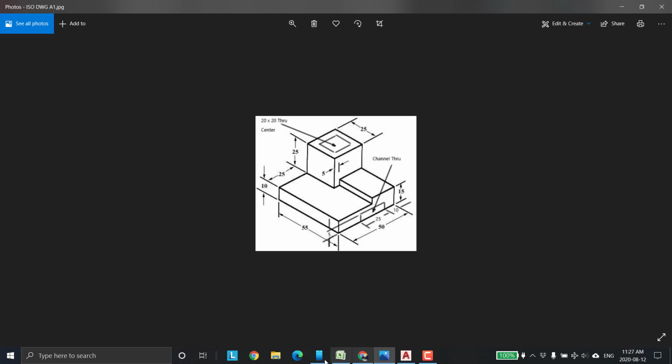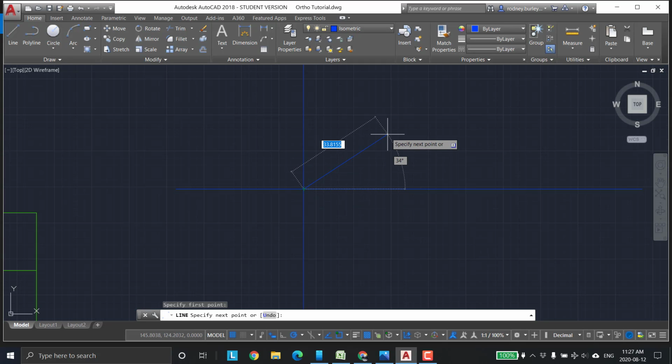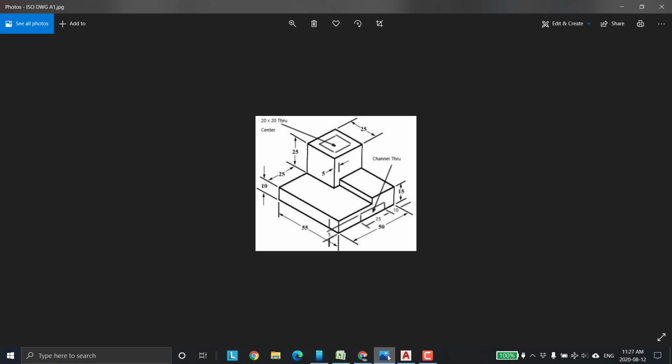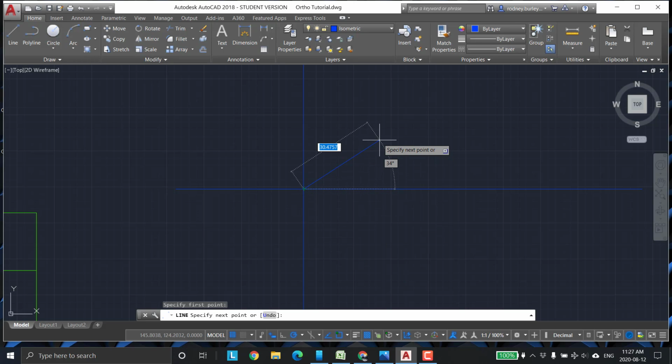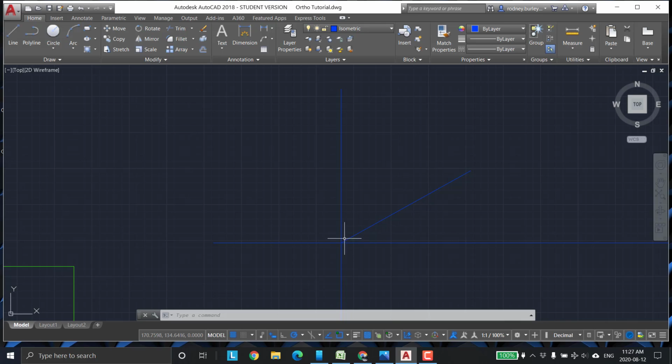You can see this is 50, and I know the angle is 50 millimeters long, so anchor it here. Again, we're on the isometric layer, which is great. Zoom in, make sure we're in the right spot. So it's 50 millimeters, and then hit the tab button, and then you can set the dimension, the angle. You can see the angle in through there. So the angle is going to be 30, enter. So it's 30 off of this, 30 off of here, and of course it would be 60 off of this, but we're rotating around this direction, so that's 30. Okay, so that line's perfect length.